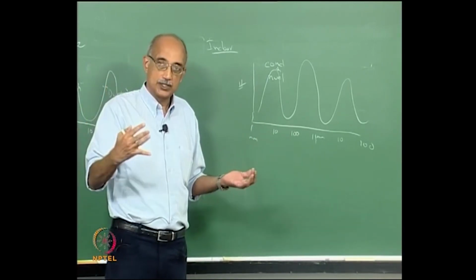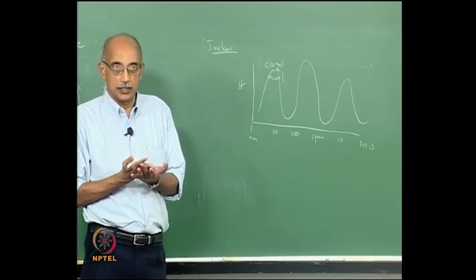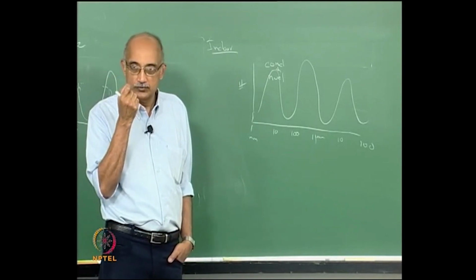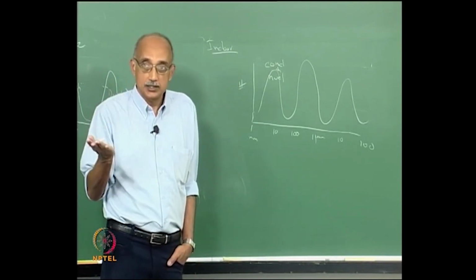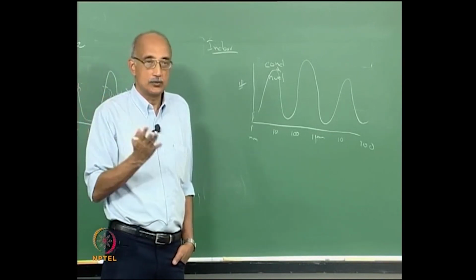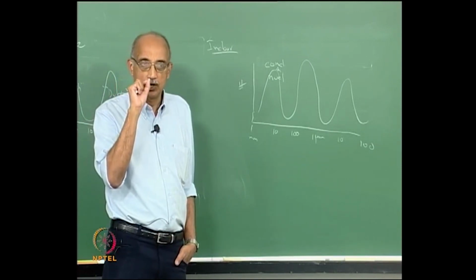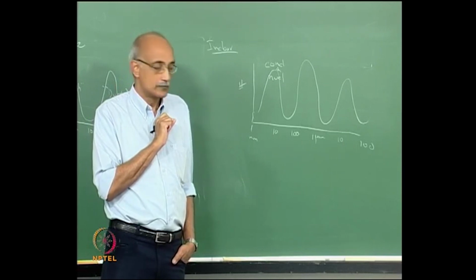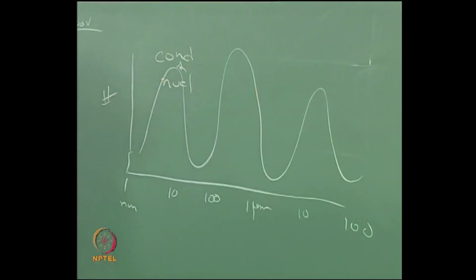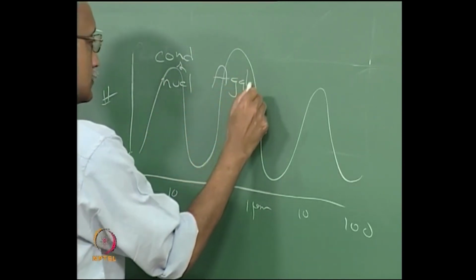So as that happens, and again as they find some heterogeneous sites to promote that nucleation, they will start nucleating very fine droplets. Again, you cannot see it, but actually if I were to, let's say, darken this room and illuminate it with a fiber light, you can actually start seeing these very fine particles and droplets in the air, right? And of course, as long as condensation and nucleation are going on, agglomeration and growth are associated mechanisms.